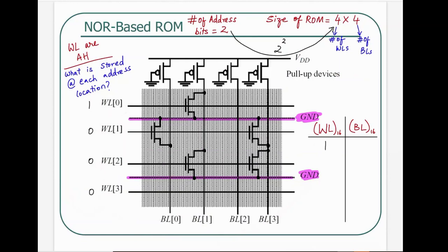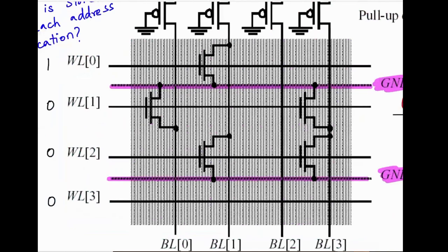So what we do here is now zoom in, and now we start noticing where is that word line connected. So each of these transistors is a NMOS transistor. And what we know about NMOS transistor is that if you want to turn it on, then you will have to give it a gate voltage with respect to source to be above a certain threshold, right?